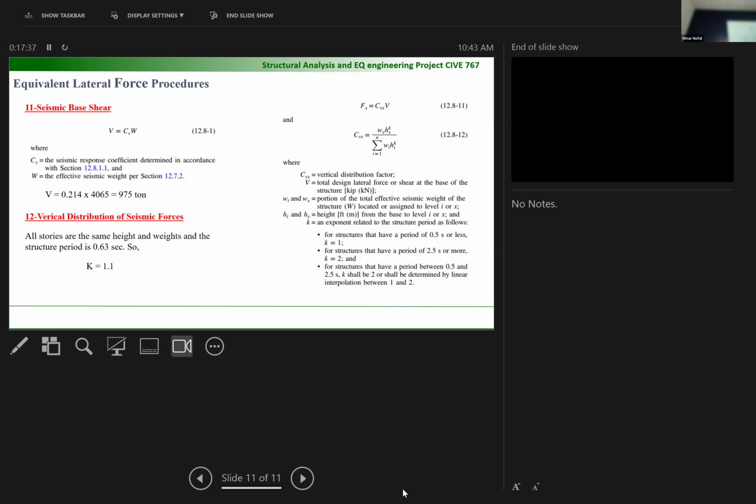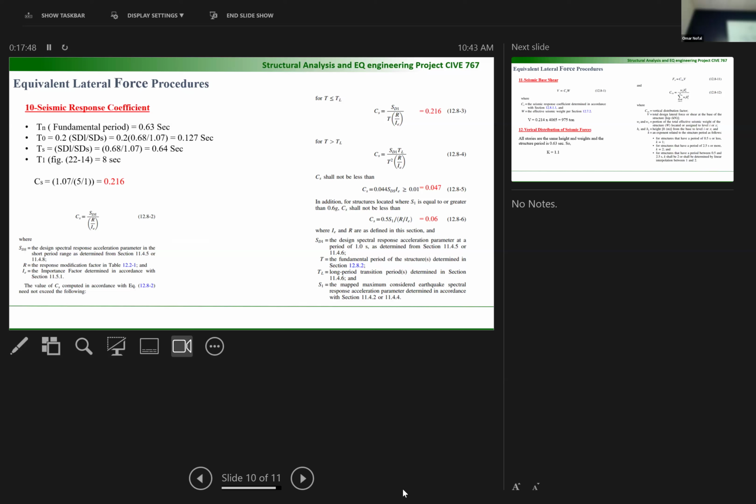It's called the seismic response coefficient determined in accordance with this section, and it has acceleration inside it. Let's see how the acceleration is inside. It has SDS, which is the spectrum design acceleration that you get from the response spectrum, divided by R. R is the reduction factor. So the acceleration is divided by R. That means that we divide the whole force by R. Multiplied, like IE should be on the top, by the risk coefficient.